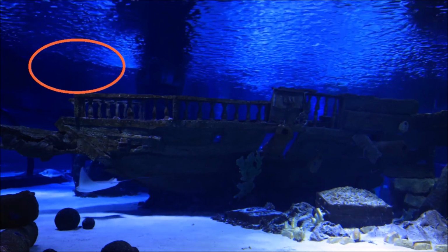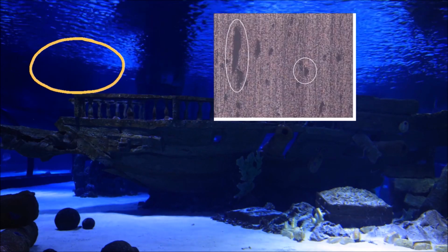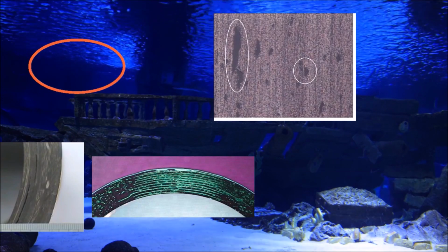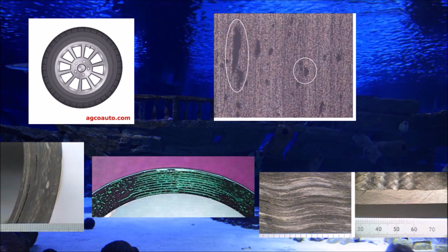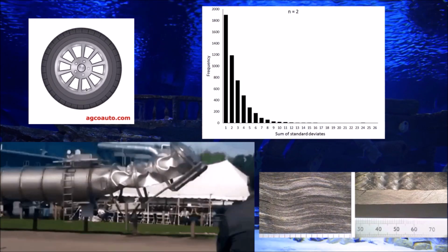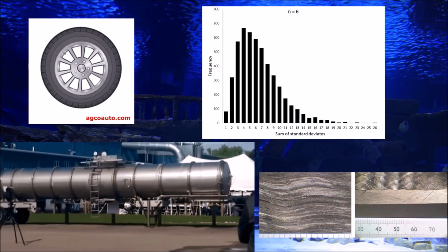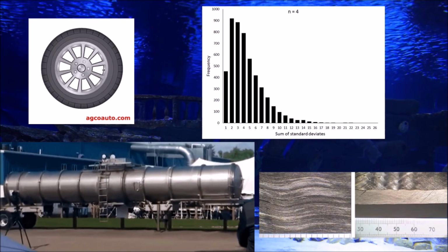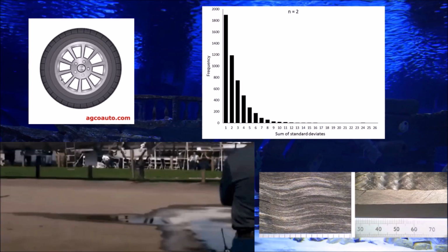So main defects include ovalization, distortion from perfect cylinder shape, porosity, presence of voids or air pockets in the material, delaminations, irregularities in fiber alignment, etc. Any geometrical deviation from cylinder, such as out of roundness or thickness variation, can initiate buckling locally and potentially lead to implosion. Porosity and fiber waviness are particularly detrimental to compressive properties. A 10% compression strength loss for each percent of porosity has been reported in the literature.